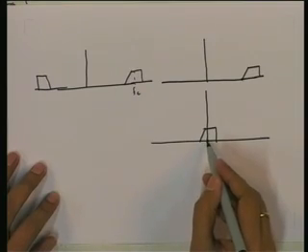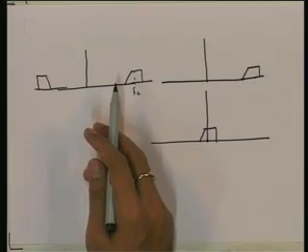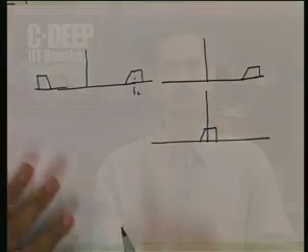We have also seen how to construct this signal, what the real part and imaginary part are in terms of this signal. And we have also seen that for a communication system, though we will be transmitting the bandpass signal through the channel, the whole system in the transmitter as well as the receiver may not be designed for that particular band which is lying at very high frequency. So, we can design the low pass equivalent signal first, because that is the baseband signal, a low pass signal with some bandwidth. Designing that signal is easier, because the processing required to generate that signal is easier, requiring low cost electronics, and then we can do up conversion to get the bandpass signal and then transmit that.